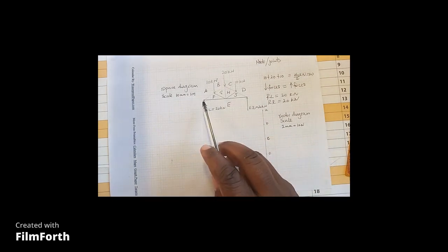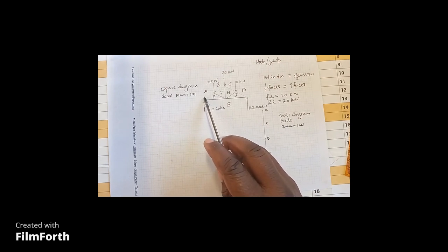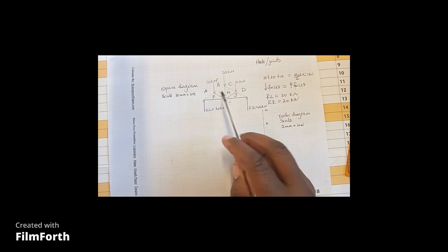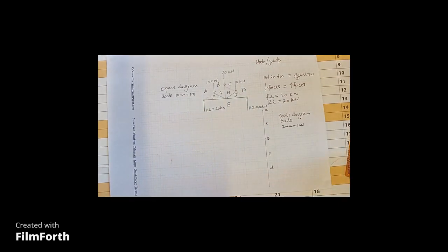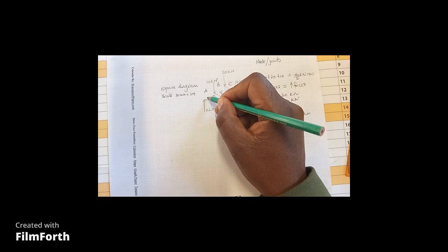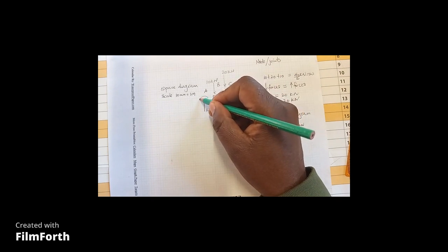Okay, so when I come at this node, because I see three forces acting on this point, this will definitely bring me to the triangle of forces. But on a joint like this one, this will bring me to a polygon of forces. We have 1, 2, 3, 4 forces acting on that node. So if I have to choose, I'll choose this node, and I want to encircle it.